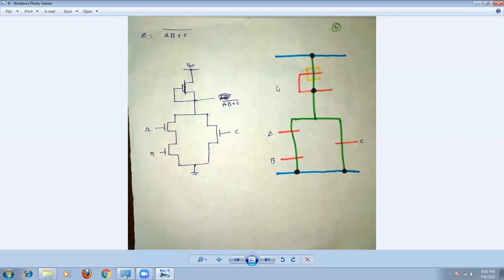Remember this point. This is the structure of stick diagrams. These are known as stick diagrams. Remember here, we can convey the layer information. These are the different layers, and we convey the layer information by use of the color codes. By seeing these color codes, we can identify that this is the transistor structure. Therefore, this is called the stick diagram, right? So that is about the NMOS design style.